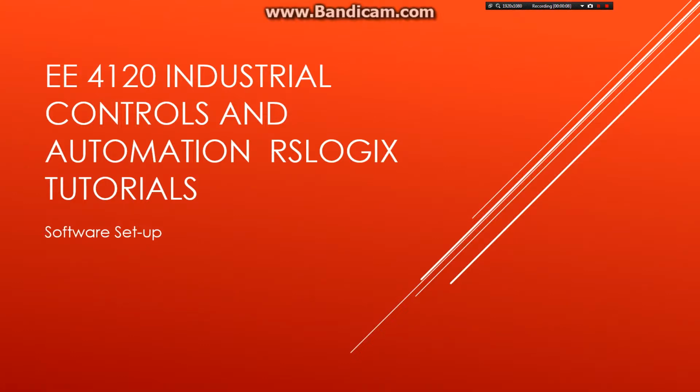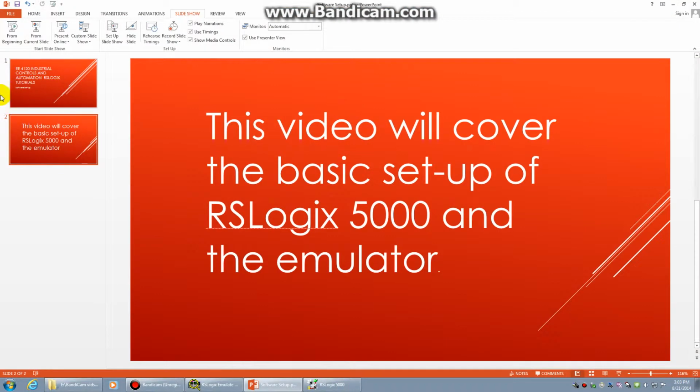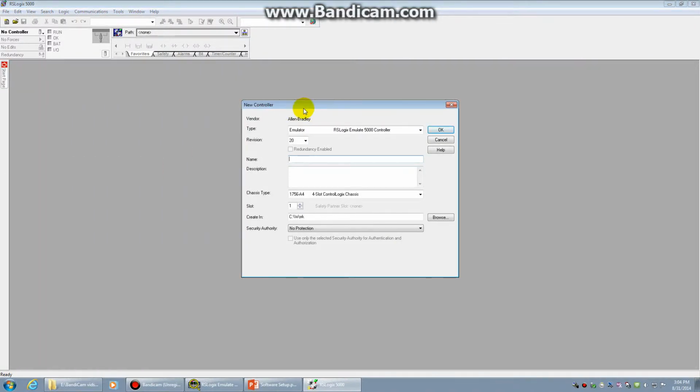This video is going to cover the basic emulator setup of RSLogix 5000 and some of the different preferences you need to set. So once you have the software up, this is going to be your opening screen. You have several different options. The first one is to open up a project that you've previously worked on. You'll see that they usually pop up right here if they're recent, or if you need to bring them from a drive. The next you'll see is the new project. Go ahead and select that.